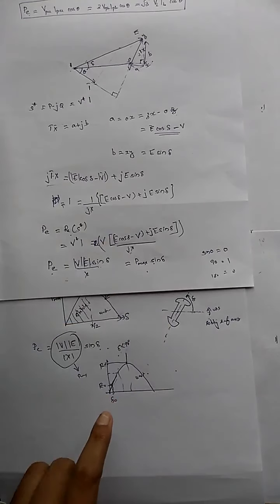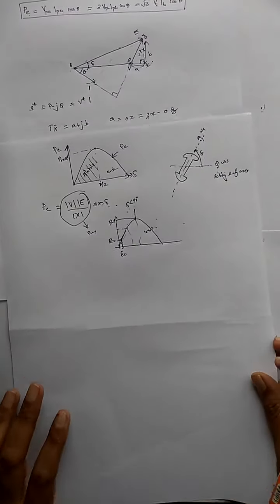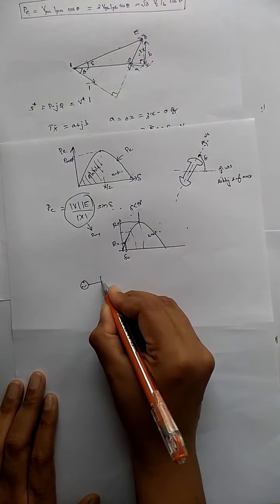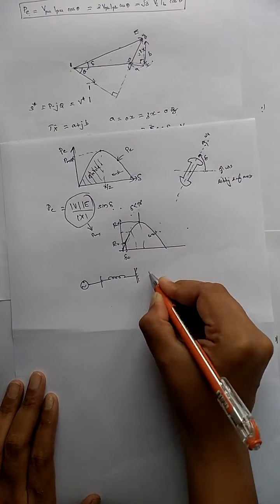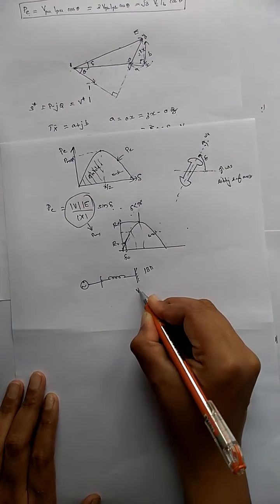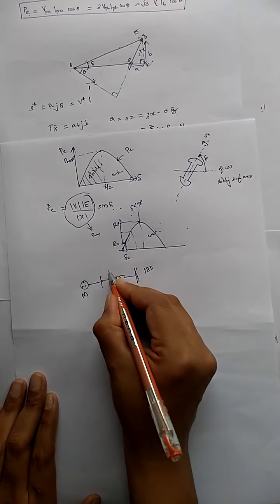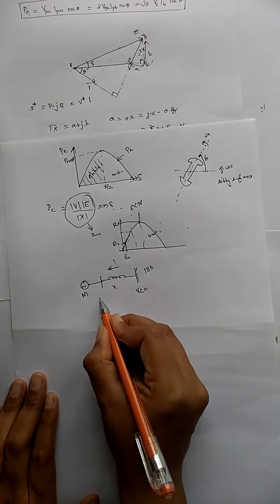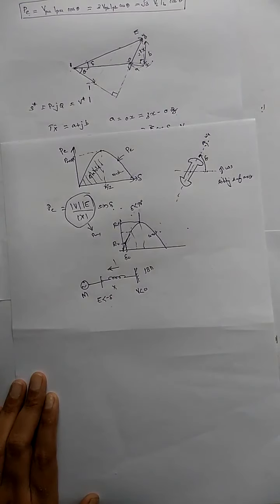So this is the power angle relation of a generator. Now very briefly I am going to discuss what happens when the machine is connected as a motor. With the same infinite bus bar, that is V angle 0, if I am using it as a motor, then naturally the current flow will be in the opposite direction. So if it is a motor, then the angle will be E minus delta, isn't it?